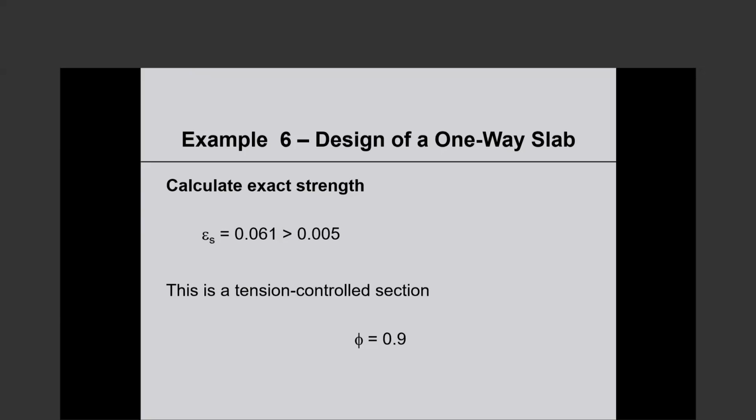So first of all, long-term deflection you cannot calculate. You probably can, but that's a research project. So long-term deflection we estimate by multiplying the short-term deflection by a multiplier that I talked about.